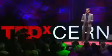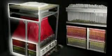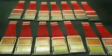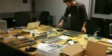Now, you might be wondering, how does this all work? And essentially what it is, is 900 linear actuators that are connected to these mechanical linkages that allow motion down here to be propagated in these pins above. So it's not that complex compared to what's going on at CERN, but it did take a long time for us to build it. And so we started with a single motor, a single linear actuator, and then we had to design a custom circuit board to control them, and then we had to make a lot of them. And so the problem with having 900 of something is that you have to do every step 900 times.